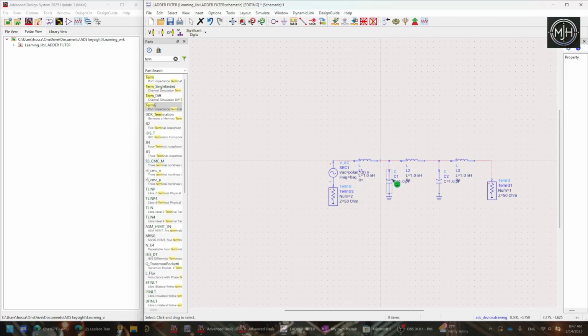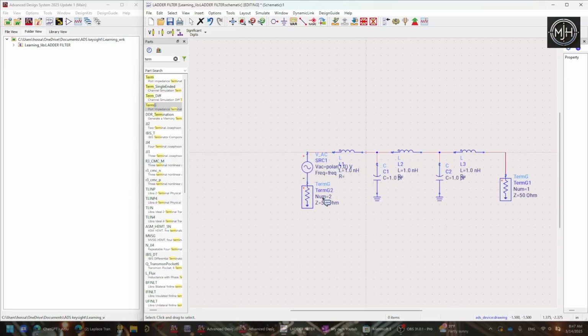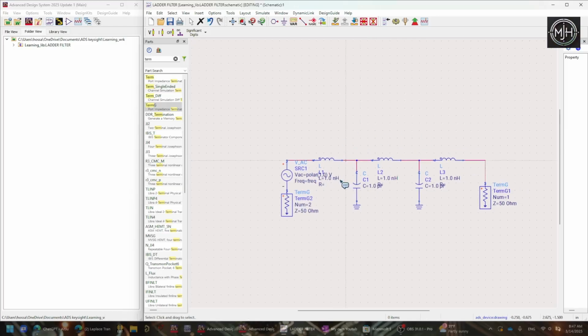All right, so that's it. Now I can do AC sweep, or I can do a Monte Carlo just to see how these things are cutting things off. You can have some exact precise values to make it a 100 megahertz low pass filter, or 200 megahertz, or 500 megahertz, or even 50 megahertz low pass filter. By this point I don't really care, because I just want to create a filter so that we have something to talk about. All right, let's just first do